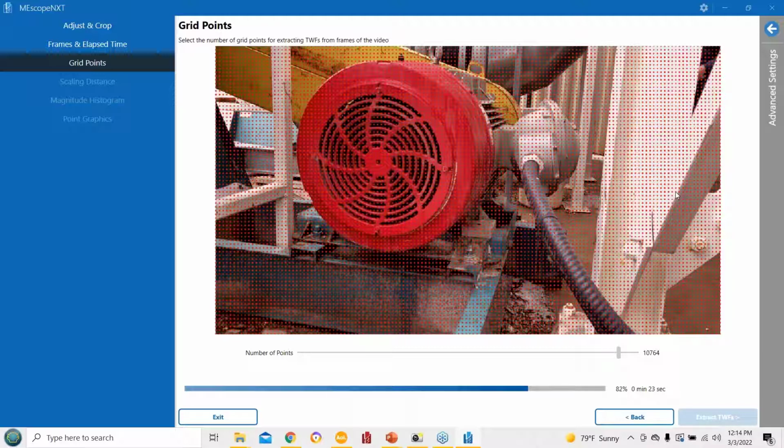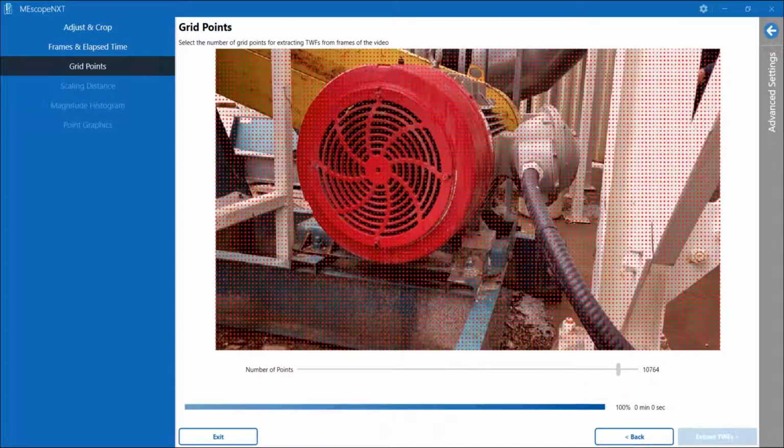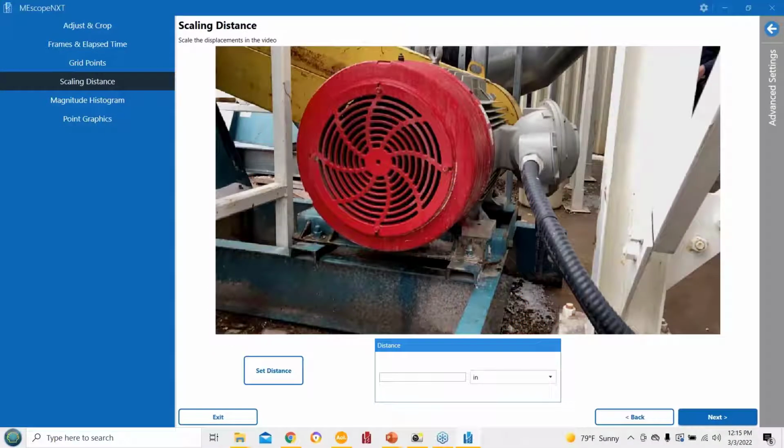Some of the data we got from this, there's several peaks, and one thing that we're going to do next week is talk about aliasing in a video clip and anti-aliasing. And in an accelerometer, you have anti-aliasing filters, or in the digital processing that the accelerometer dumps to. We have hard analog filters that will chop the vibration off at Fmax. That doesn't occur in a video clip. There will be frequencies above Fmax that fold back into the signal that'll give us problems. And we're going to locate and remove those next week.